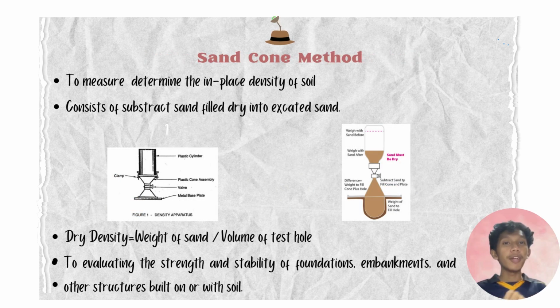So today I'm going to discuss a little bit about the sand method, which determines the in-place density of soil that consists of substrate of sand filled into the excavated area. First thing first, the dry density can be calculated by weight of sand divided by the volume of the test hole to evaluate the strength or stability of foundation, embankments, and other structures that are built on it. It is only applicable for granular soil and hard soil, which is suitable and easy to initiate as a site